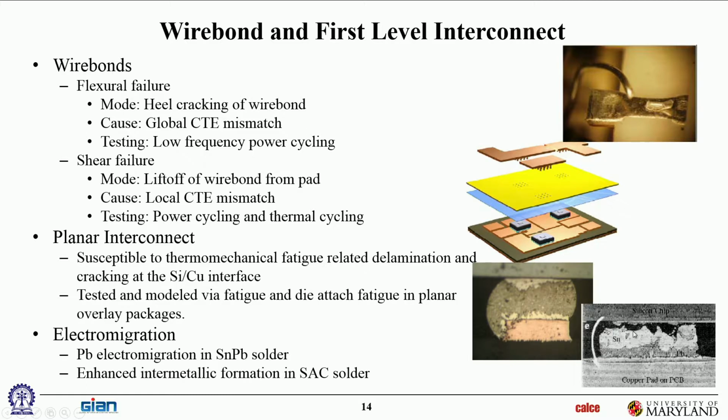So the current density sometimes in solder joints will be so high that the same thing that happens in aluminum traces, it knocks out metal ions from the lattice, same thing happens in solder joints. It knocks out metal ions from the tin lattice, and you start to grow these depleted regions, which then are even more vulnerable to thermomechanical cyclic fatigue. And they kind of hurt each other, so they collaboratively fail the solder joint. Also at those very high temperatures, you get excessive intermetallic growths. So that embrittles the joints. If there's any kind of harsh mechanical stress, you get vibration failures at those intermetallic joints.